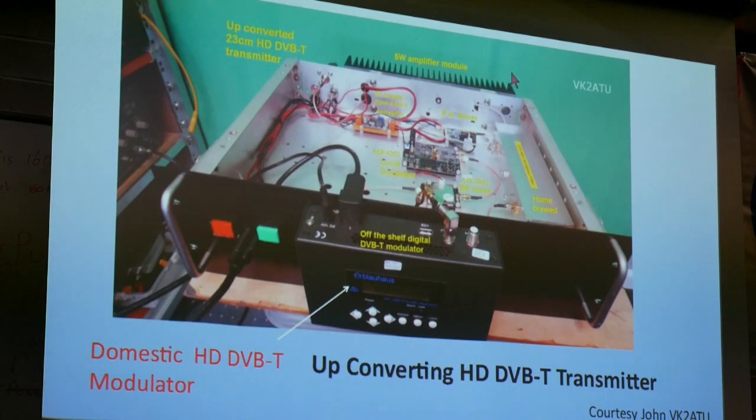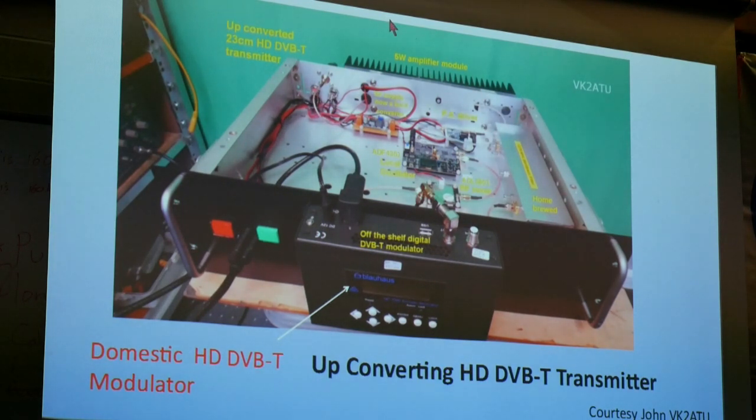And with DVB-T you need a really linear amplifier. So this is the problem with DVB-T. You've got a crest factor, which is the peak to average power, on a DVB-T modulator of at least 10 dB. So that means if you wanted to get 5 watts average power out of this, you need at least a 50-watt amplifier to handle the peaks. Hence, DVB-S is much easier to transmit because you can get away with a much crappier amplifier, basically.